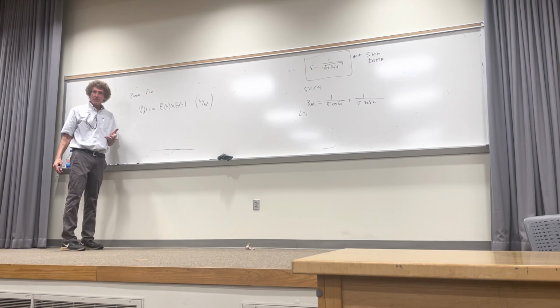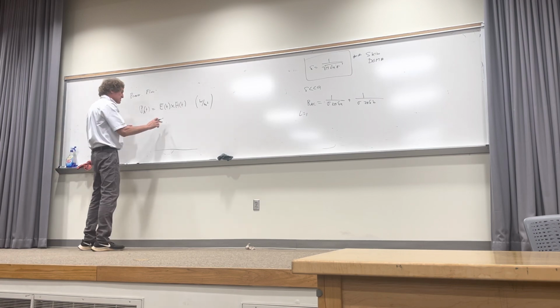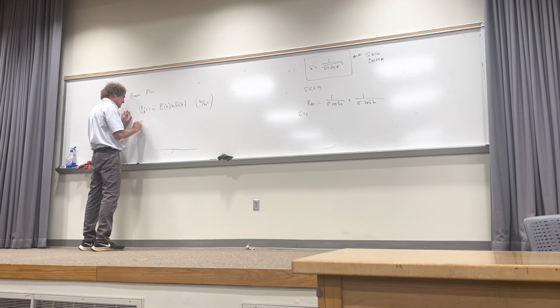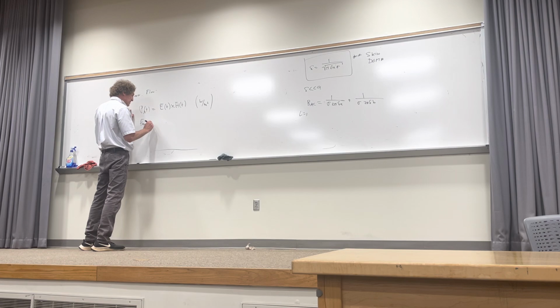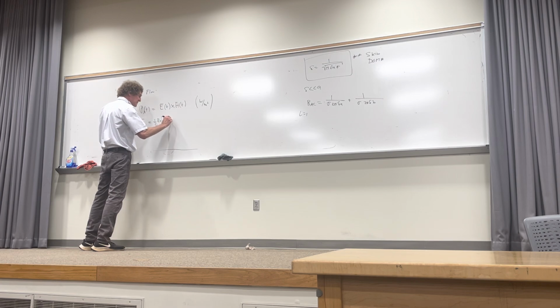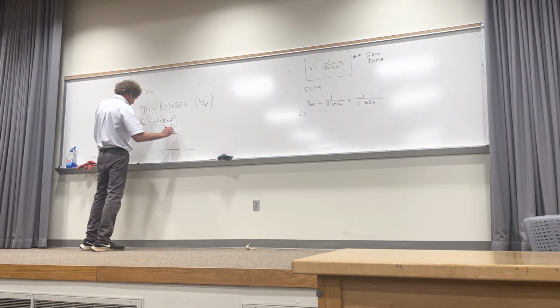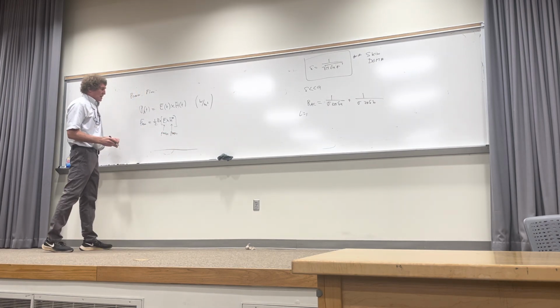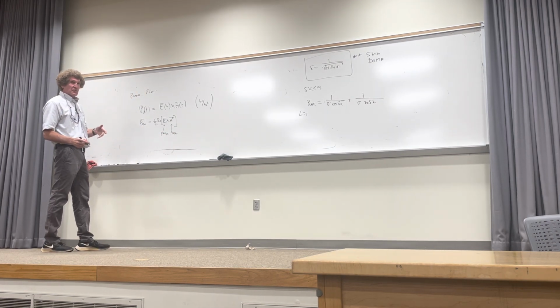This is power flow. And when you do this, what we usually talk about is the average power flow. This one you write down. Average power flow is 1/2 the real part of the E field crossed into the H field conjugated. And these are phasor terms. Now, I'm going to go through this next time. I'm just trying to set you up for this.